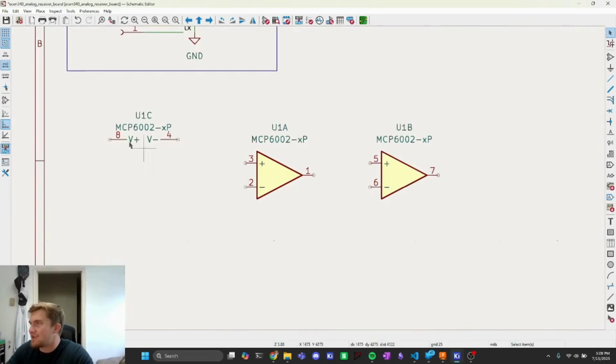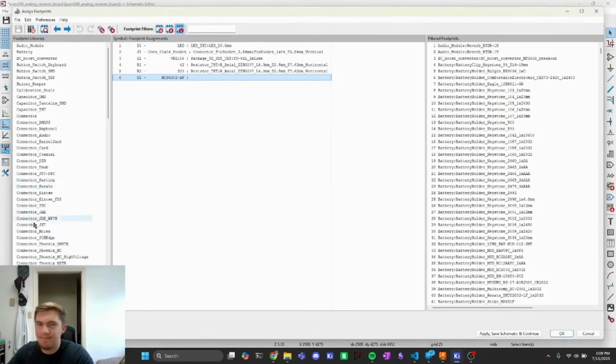Now that we have this here, you can do this. That's the fun LTSpice part you designed and implemented on a breadboard. You know how to wire these up. I'm going to let you do that. But we are going to go to assign footprints to give it a footprint, because it doesn't automagically come with one attached. We are friends, however, so I will find it for you.